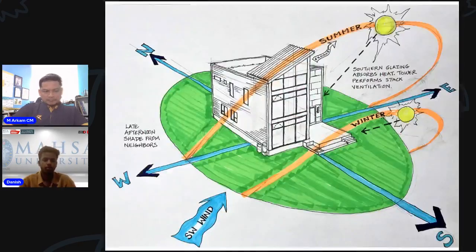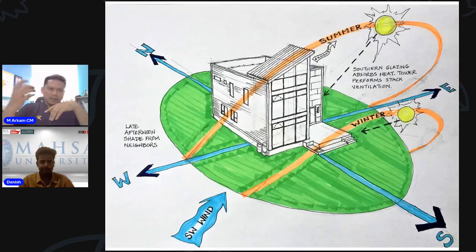Okay, beside the sun, we have about two things. First one is the heat. Second one is the intensity of the lights. The intensity of the lights translates into the lux level, the illuminance level, so that we can have visual comfort. And heat goes for thermal comfort, where we can get the temperature going up or down. Temperature is the same terms, either heat, either high or low.